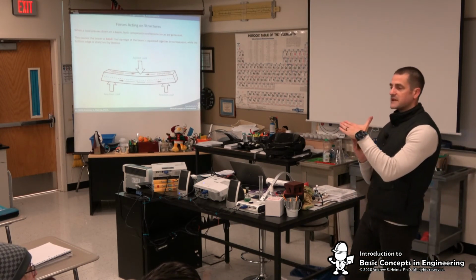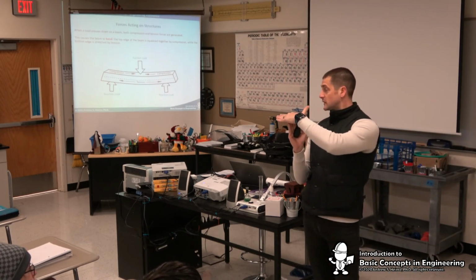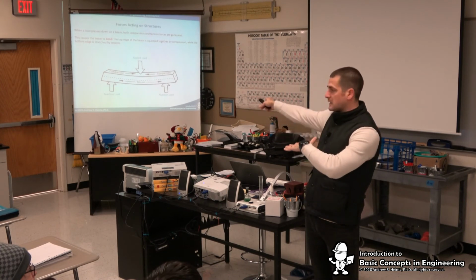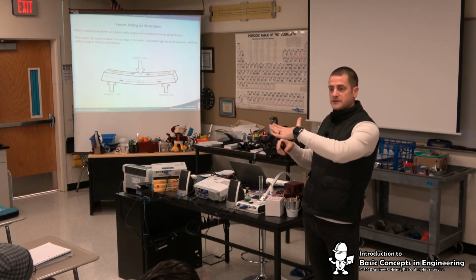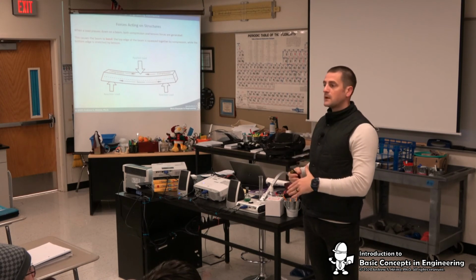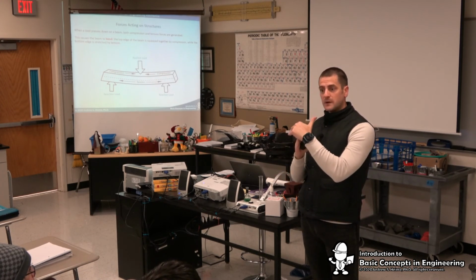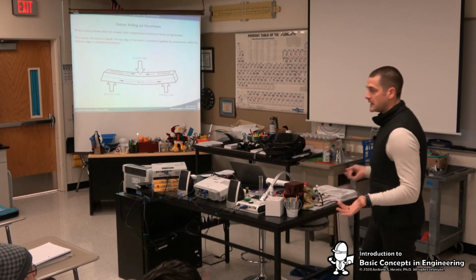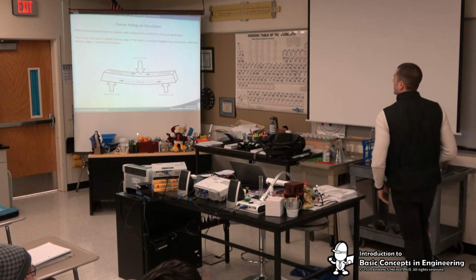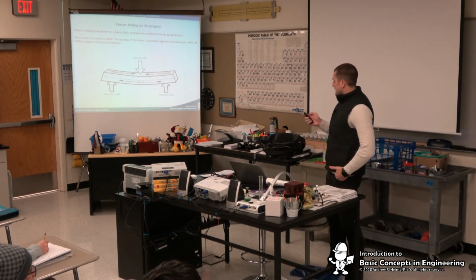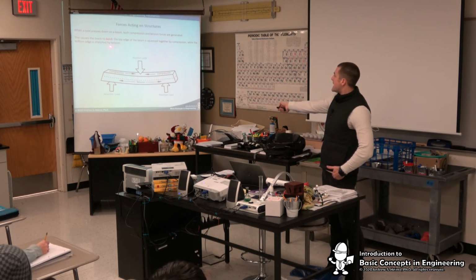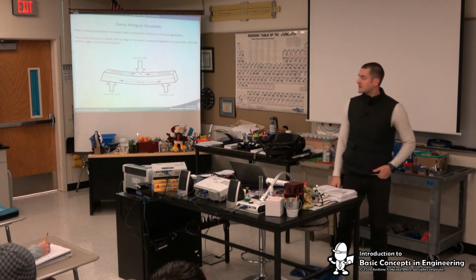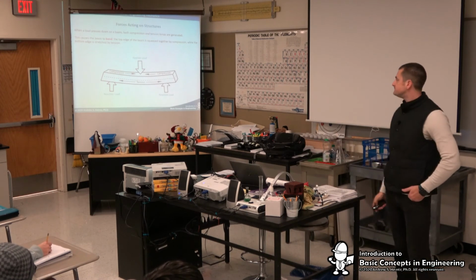And when you typically see it crack, it'll either fall in, which would be the opposite case here, and you'd see it crack from the top, or you'll have something like a root come up from underneath, press it, and then it bends again, and you see it crack in that fashion. Make sense? Okay. So yes, this causes the beam to bend. The top edge is squeezed together, and the bottom edge is stretched.